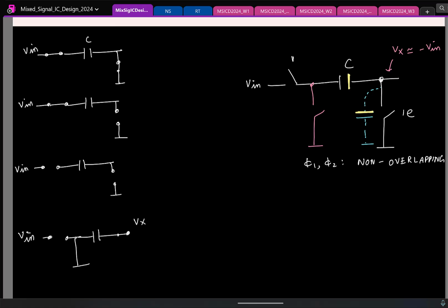We also saw that if we were to process this voltage, ideally we should not be drawing any current from this guy, because the moment we draw any current, we are losing the charge stored in the capacitor, we lose the actual input information. So we can either use an open loop buffer, or a better deal was to do the following.